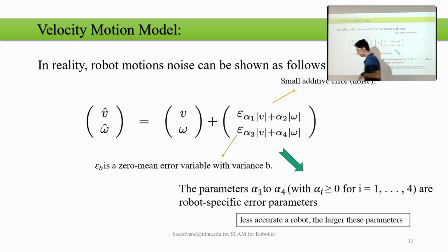And where do those come from? Again, we need to test it. Simply, you test your robot from here, you run the motion command move forward. If it's completely straight, that's nice. But if it ends up a little bit to the right or a little bit to the left, you add the error. You adjust the parameter here for moving forward. What is the error of the straight movement or rotation?